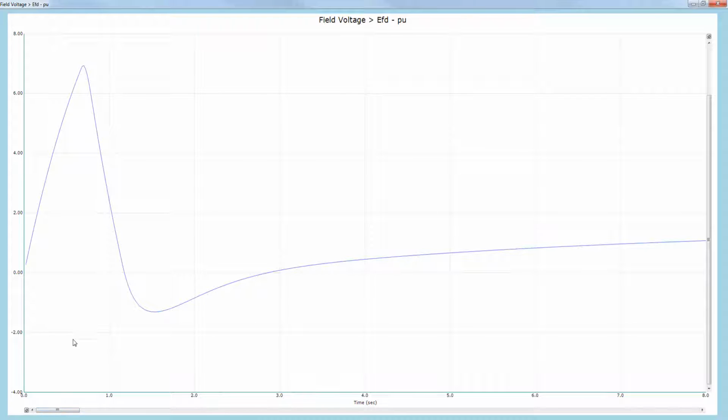Many times during this initialization process, we may hit some nonlinear conditions and reach clamp values, which prevent the internal states of the exciter from reaching its desired steady state values. This will produce what we know as fail to initialize problems in the model. And this test routine transfer function that I'm providing with this webinar can be used to observe the internal states and the behavior of the element during excitation, and also help you to correct the problems by identifying them.